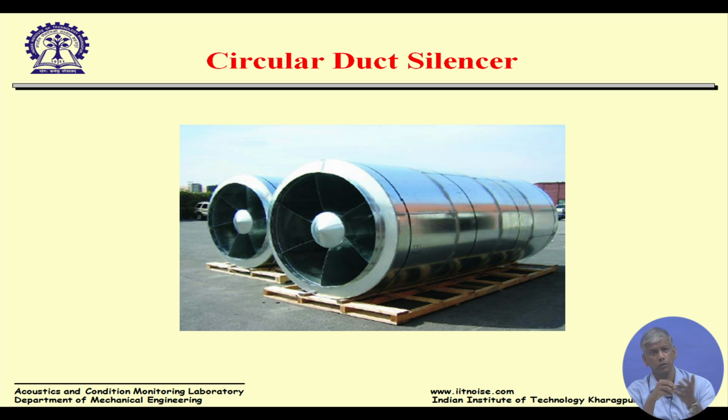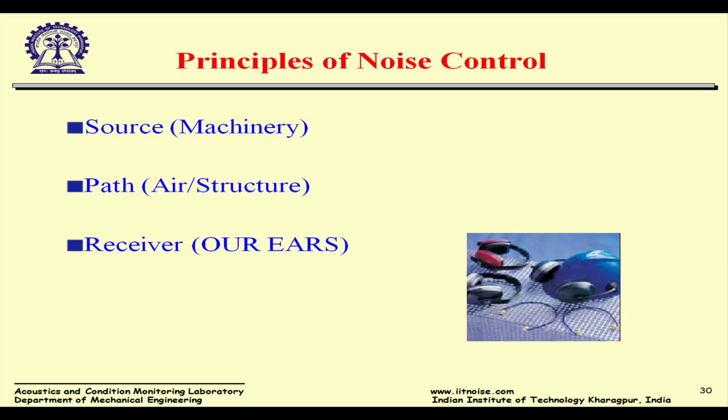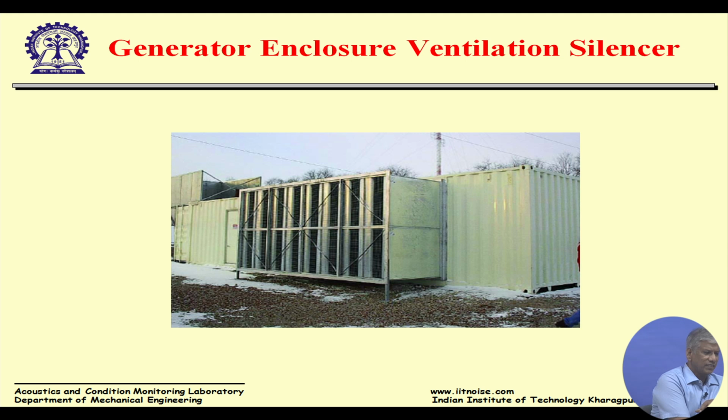For example, another issue is steam ejecting out of a pipeline, because steam is generated from a boiler. I cannot shut the boiler. The boiler is always on, and if the steam pressure builds up, the safety valves will open up and make a hissing noise, and these are irritating. They add to the environmental noise. So we have to design vent silencers wherein we can reduce such exhaust noises because of the steam exhaust at high temperature and high flow. Okay. Well, if nothing works, please put in ear muffs and plugs and so on. These are just some views of some work I had done somewhere.